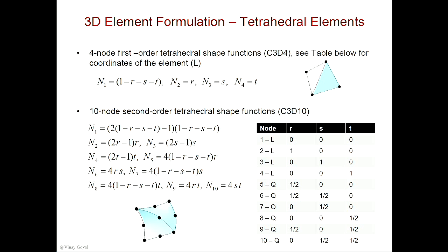Okay, very, very good element too for 3D problems. The linear tetrahedron here, not as good, because this is a constant strain element. This one gives you a linear distribution of strain across the element, so it's very good. Quadratic interpolation across every edge, that's still a linear strain. Really good element. This one, not so much. It's constant strain throughout the element.